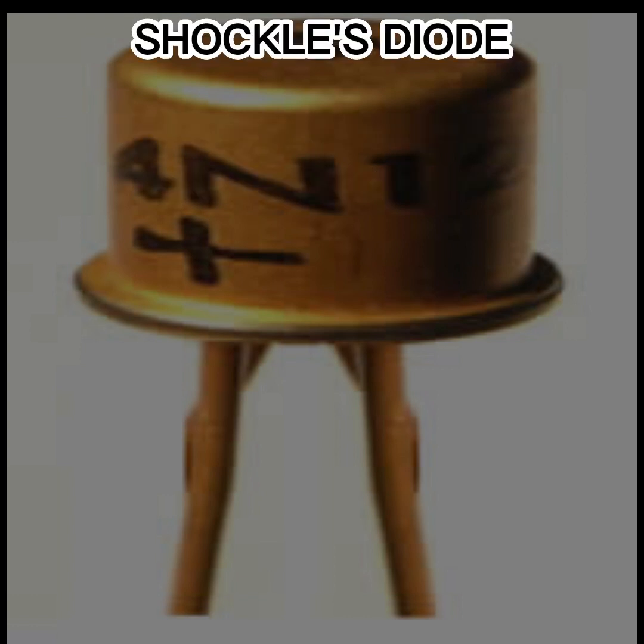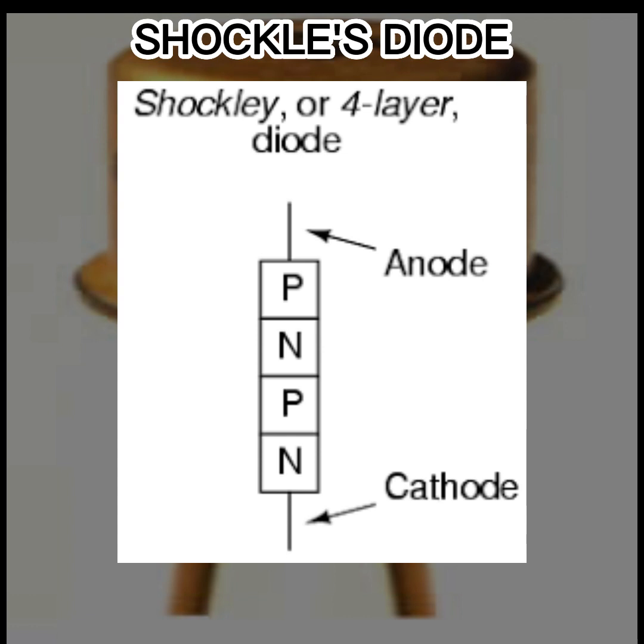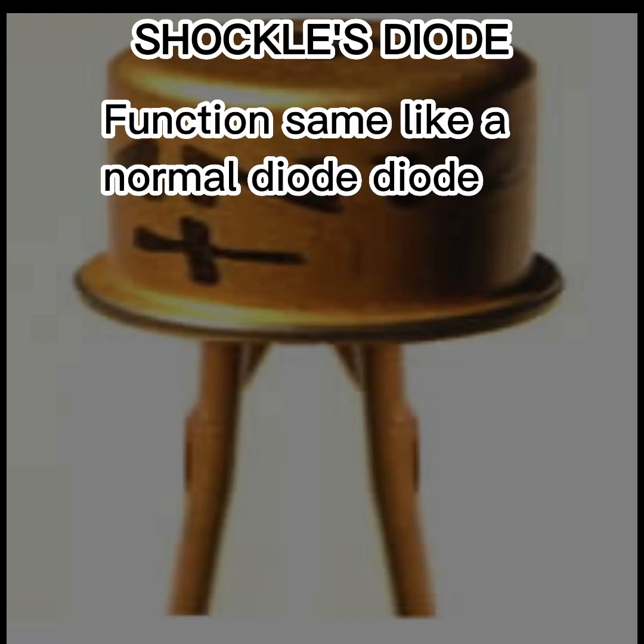devices. The Shockley diode or PNPN diode is a four-layer, PNPN, two terminals, namely anode and cathode, semiconductor switching device. It is also called a four-layer diode. It functions like a normal diode without any trigger inputs.